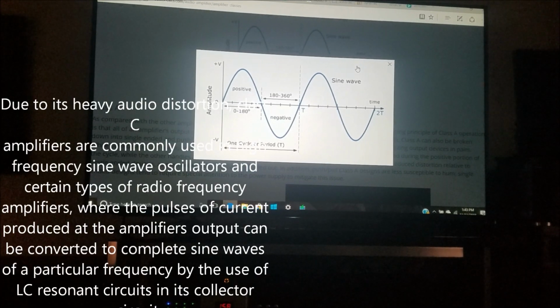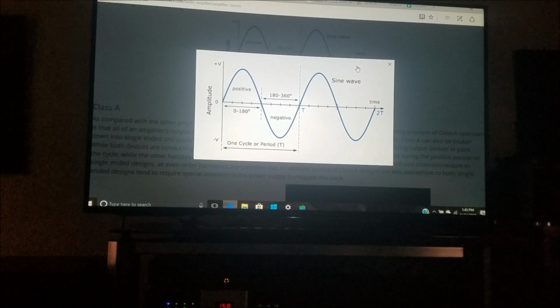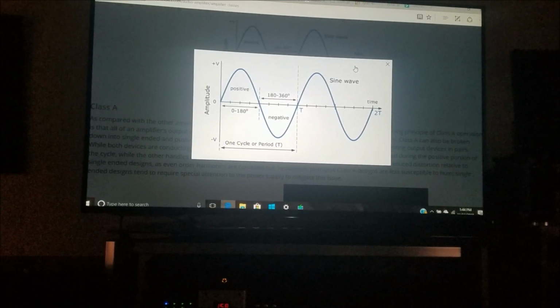But technically the thing to remember in Class C amps, now think of radios and transistor radios and whatnot, is that the active element conducts only while the collector voltage is technically passing through its minimum. Power dissipation in the active device is really minimized, and efficiency is really at a maximum. But usually it's stuff that's operating on a single fixed carrier frequency.